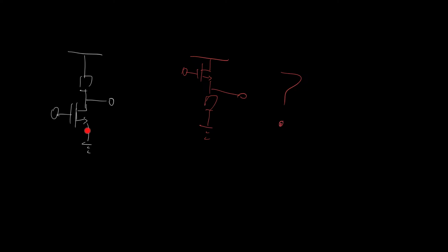We've explained that this is how we build an inverter, although ideally this is a P-channel FET, and it's natural to ask, well, why can't I just put an N-channel FET upstairs? Would this then function as a buffer? And more generally, if we take our NAND gate, if we were to just put the N channels on top and P channels on bottom, won't we get an AND gate? It's a natural question, but this is not going to work.